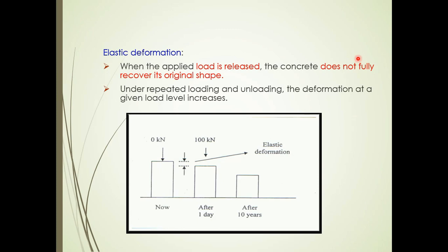In elastic deformation, when the applied load is released, the concrete does not fully recover its original shape. So in some concrete, the concrete does not recover its original shape. It has a small amount of deformation. So under repeated loading and unloading, the deformation may increase.